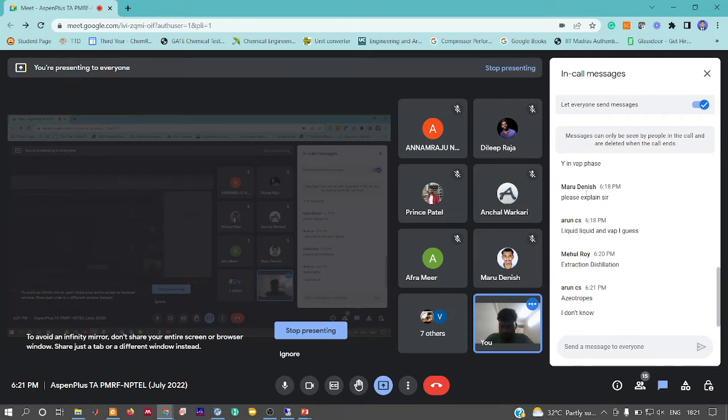I don't know. Okay, fine. See, essentially, I was asking whether you're discussing a homogeneous azeotrope or a heterogeneous azeotrope. That was my question. So, if you are talking of VLLE, then it's a heterogeneous azeotrope. That was the word which I was expecting. Fine, no issues. Yes, in extractive distillation, you always introduce an entrainer to your system, extract some of the required component, and then send it to distillation.